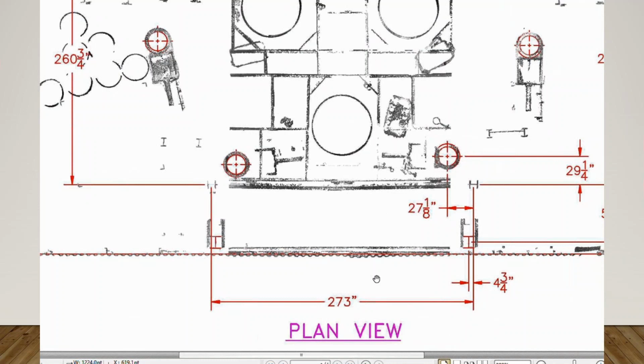And you can cover a lot of ground. In an open space, the laser scanners are capable of going 200, 300, 400 feet. Most of my scans happen in industrial situations, so I'm only moving the scanner probably 10, 20, 30, 40 feet at a time. So it's better to take more scans with less density, and you'll have smaller files also.